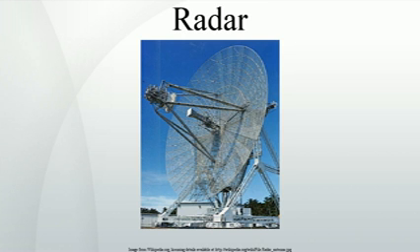Jammers therefore can be much less powerful than their jammed radars and still effectively mask targets along the line of sight from the jammer to the radar, main lobe jamming. Jammers have an added effect of affecting radars along other lines of sight through the radar receiver's side lobes, side lobe jamming. Main lobe jamming can generally only be reduced by narrowing the main lobe solid angle and cannot fully be eliminated when directly facing a jammer which uses the same frequency and polarization as the radar.